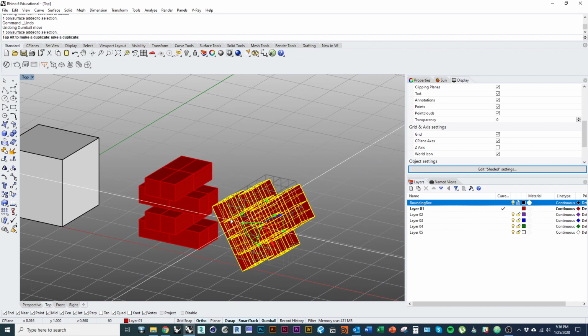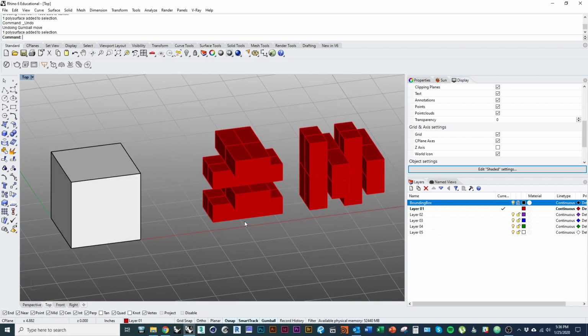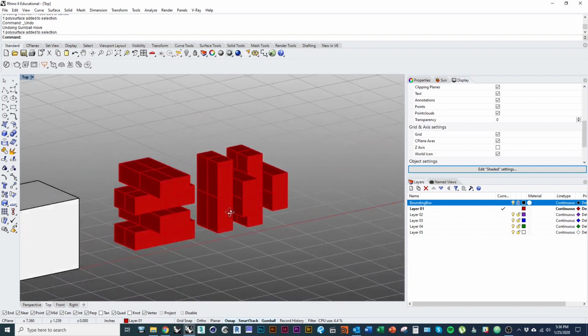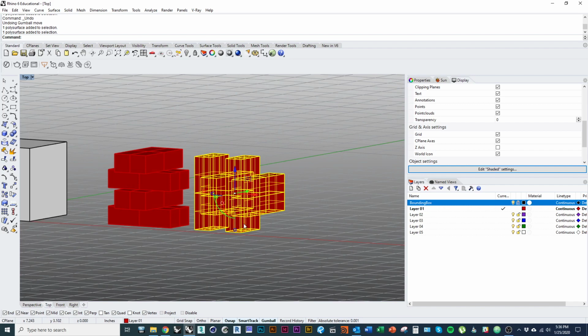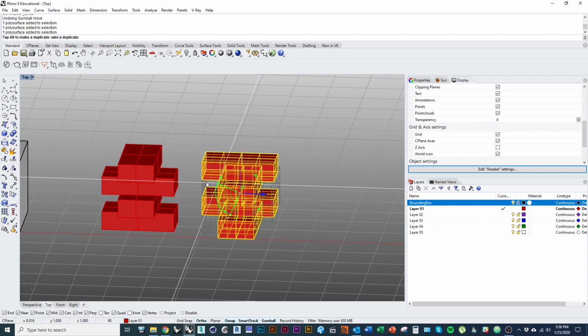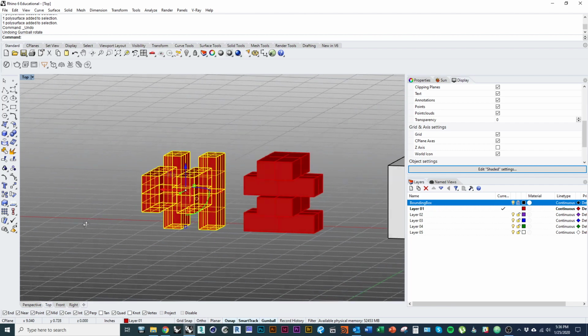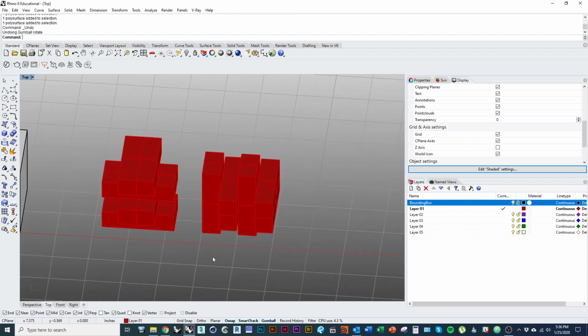And then I think the other thing that is good to pay attention to is what orientation makes sense for 3D printing. So with this geometry, by definition, I am going to need support in order to print it, right? So there's a couple different ways I could deal with that.